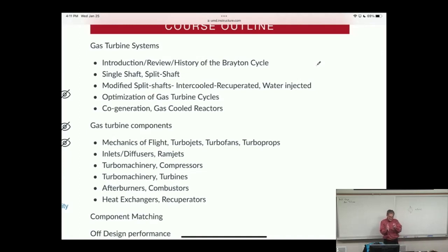And there's a little bit of a sailing component because the compressor rotors are airfoils. So we're going to have pressure loads and how much of the compressor spinning is impulse, how much of it is reaction, meaning a delta P across the blade, like Bernoulli's equation. That's how an airplane flies, through a reaction force. So it's not the circle with the thing on it. For the first 5 weeks, it will be. And then that'll all change with vector diagrams and all of that.